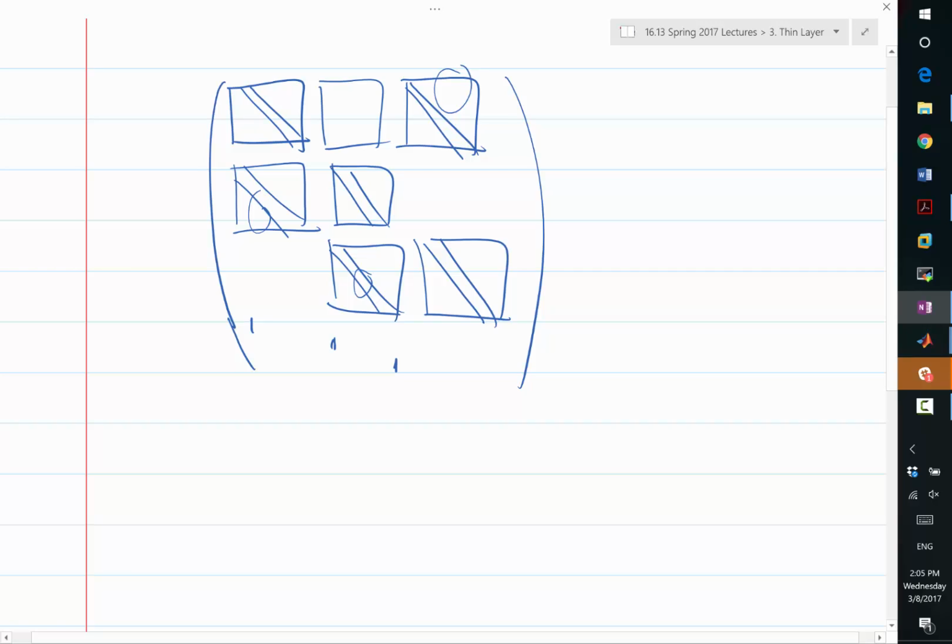There are all these coupling terms that couple everything together. It's the same type of matrix we are going to get in the coupled inside-outside boundary layer and inviscid flow system. Each diagonal block corresponds, for example, to how the boundary layer influences itself. So this whole thing is going to be a diagonal block for that coupled system, and the outside inviscid solution is also going to have its own diagonal block.